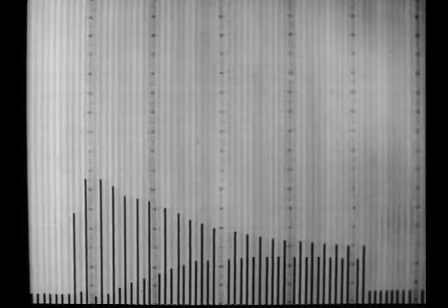When stalled, this profile suffers a loss of lift. As suction is applied, lift is restored. As the flow is reattached, the pressure distribution approaches that of an inviscid flow. The irregularities in this pattern occur where the pressure taps are located near the suction slots.